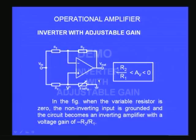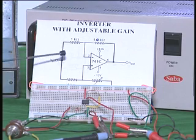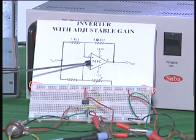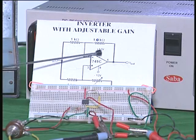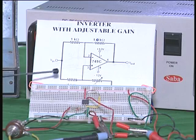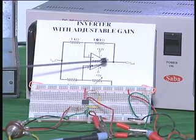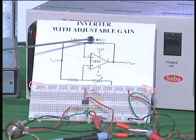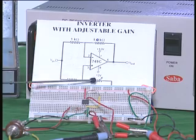I will also show you a demonstration of this circuit. Now, I want you to observe the circuit here. It is the same as the one I showed you just a few minutes ago. You have an operational amplifier 741 and you have a 1K resistor here, here also 1K, and this is also 1K. So both are equal, and I have a variable resistor, a potentiometer, here. When I vary the potentiometer from 0 to a maximum value, the gain should go from minus R2 by R1, in this case minus 1, to some different values. I can vary it by varying this potentiometer. That is what I wanted to show you. You can vary the gain by changing this potentiometer.